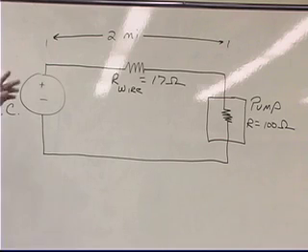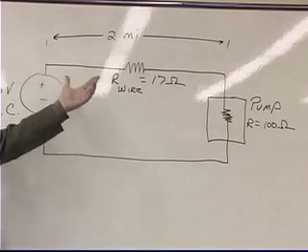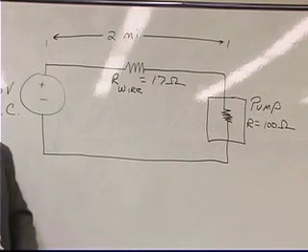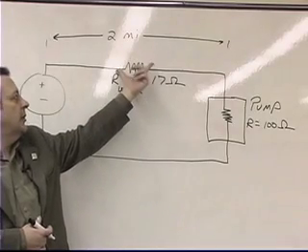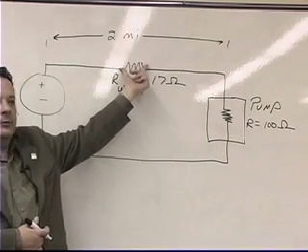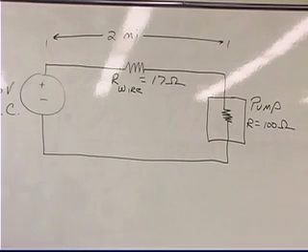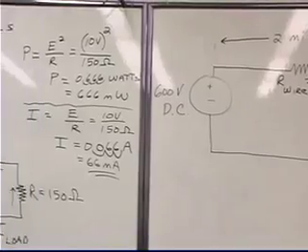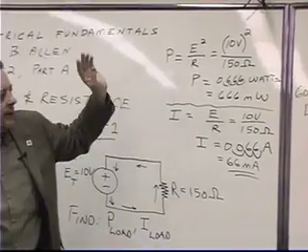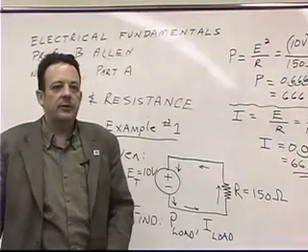So in other words, what I'm using is what's called a lumped parameter model, where I'm taking the whole 2 miles of resistance and lumping it into this one little space. Thanks for asking that question. So that whole 2 miles of wire has a resistance of 17 ohms.